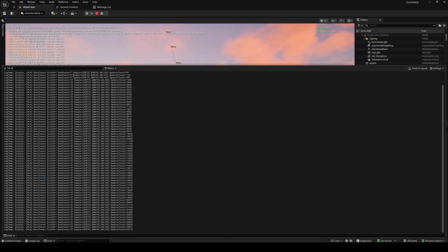So, one button joins the Federation execution. Clearance registers as the clearance instructor federate, passes my extension from XML, resolves object class and attribute handles, declares publication, and starts pushing attribute updates on every aircraft in the sim to the RTI. As you can see, the updates total is climbing. That's every update attribute values call that the RTI ambassador accepted.